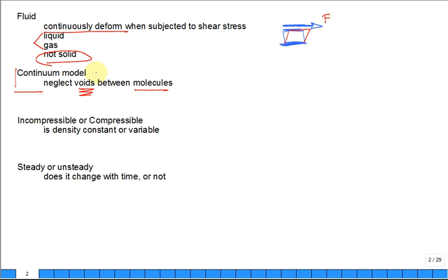So most of the space is filled with voids or vacuum, and very little is filled with chunks of material flying around. But what we do is we say it's smooth, it's a continuum, and that's our fluid. We neglect that void nature of the material, unless we go down to rarefied flow conditions, then you do have to worry about it.